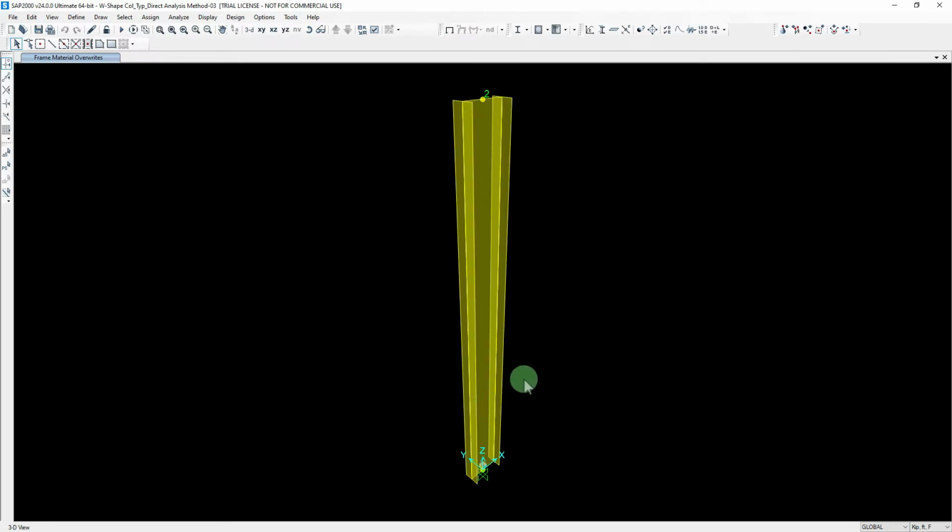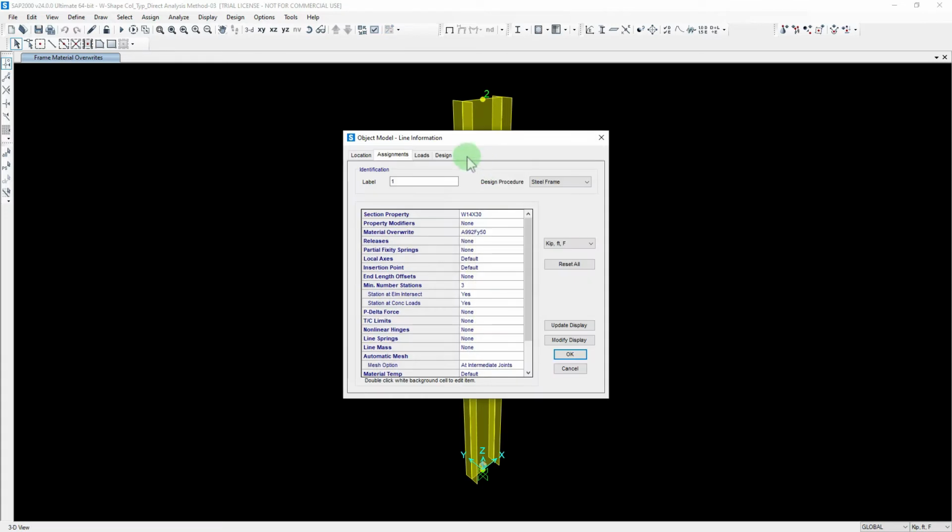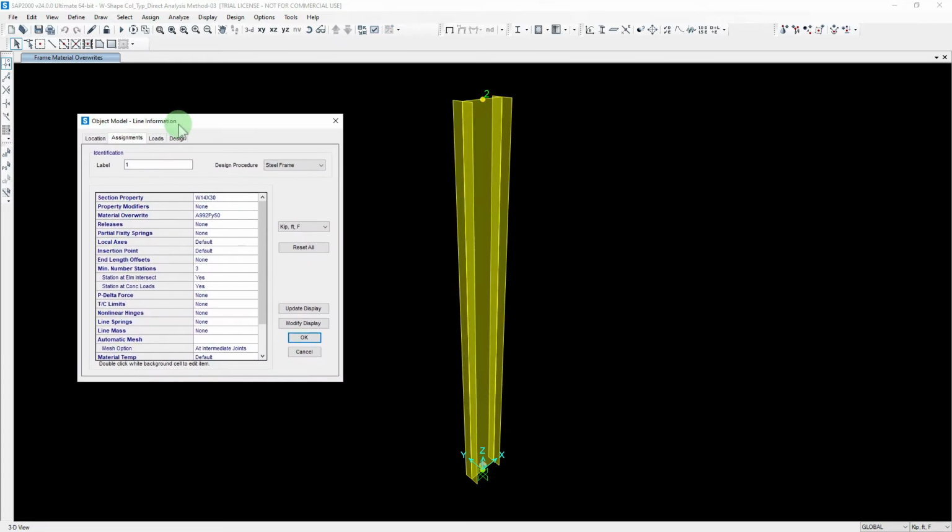So now that I have the structure defined, I have my cantilever column that's defined. It has the proper sections. I could double check that by selecting it with a crossing window that turns into dots, or a crossing window the other way. It also turns into dots, and you select it. Now you can right click. You have to right click on the line.